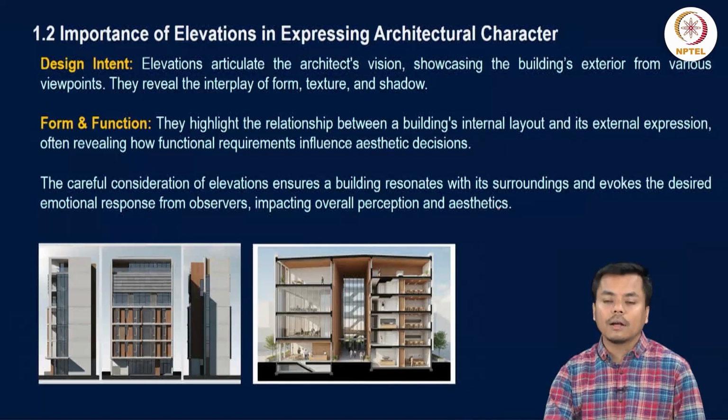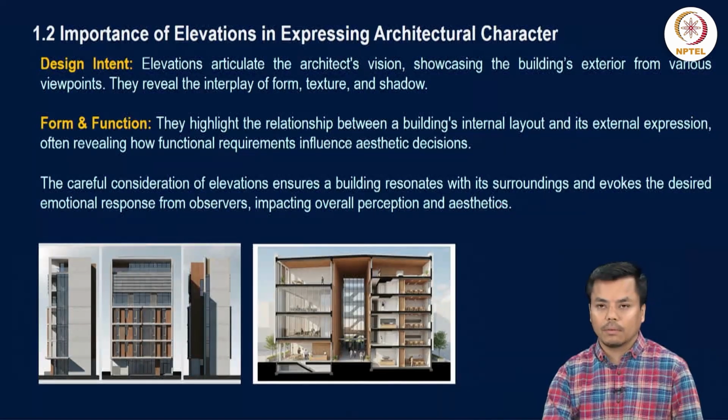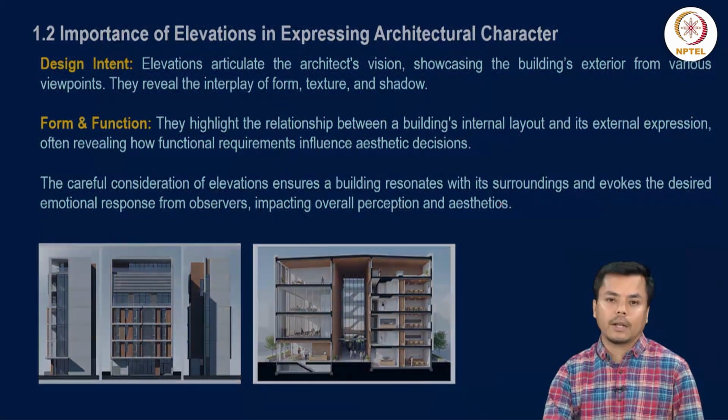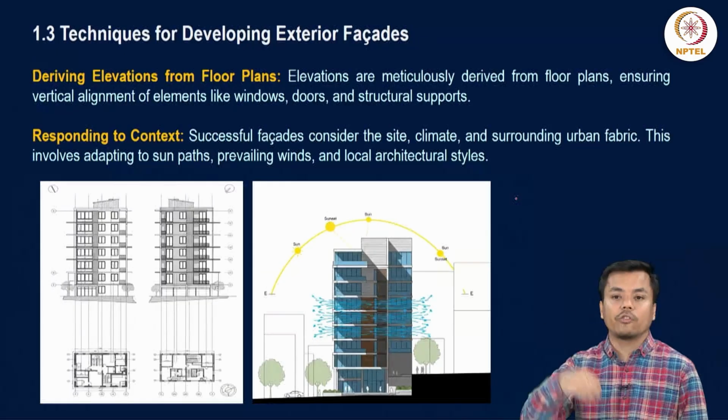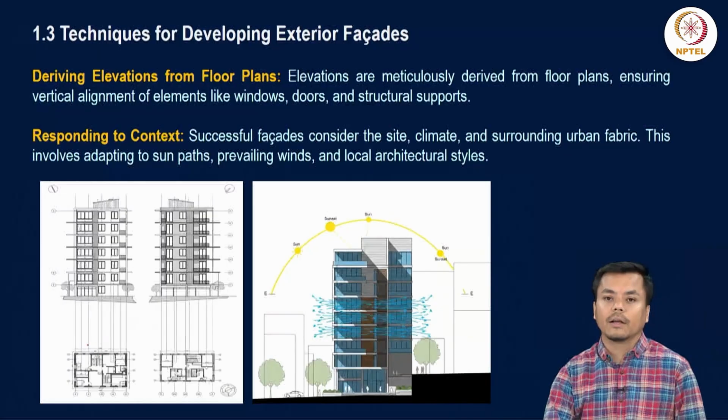So these two have to be followed when you prepare your elevation, along with some other techniques for developing the exterior facade, which include deriving the elevation from the floor plan. We generally project our lines as shown here. We project all these vertical lines to draft the elevation.